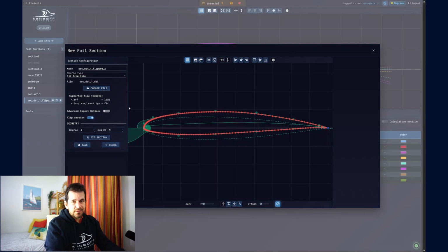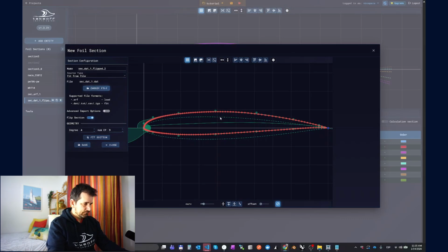And then the final one, which is very, very useful, you can have an IGES. And that is a big jump and a big commodity to import some sections. So basically you can have a closed section, an open section on the trailing edge, and it can be in any position. So you don't need to calculate it and put it into a 2D plane and then put it at chord 1 and then rotate it. You don't care about that. You just have any section in any position.